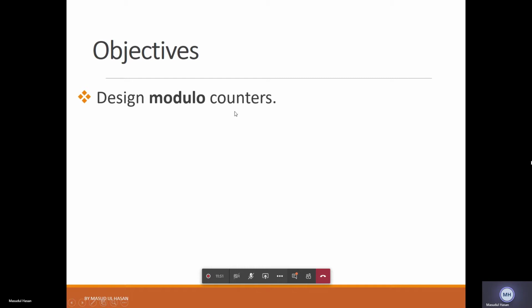So it is like a BCD. Whatever your numbers are, you always need 4 bits. So you must put 4 bits here. Don't make it 3-bit, okay? Just change the name modulo 6 instead of mod 10, make it mod 6, and change here: counter equal 5. Nothing else should be changed. So in your case, this will be mod 10, this will be mod 6.